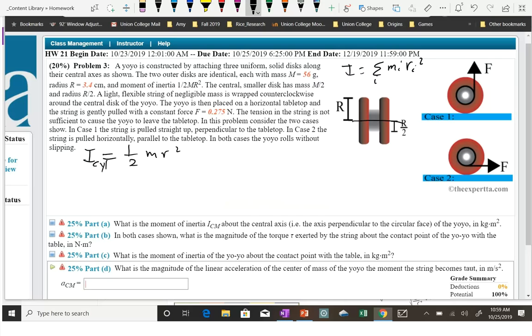We first talked about it when Andy was sitting and spinning, and then we reviewed it again when we had the lecture in lab on Tuesday. So the moment of inertia just comes from adding up all of the pieces of mass times their distance from the rotational axis squared. So if I have one thing and I know adding all of its pieces up gives me 1/2 the mass of that object times the radius of that object squared, and then I go to another one, if I add all those up, it's going to give me this equation.